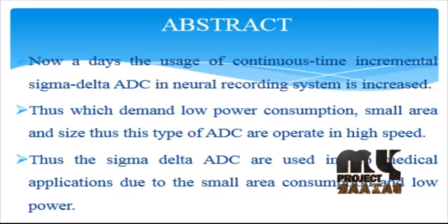This two-step architecture is also power efficient as the resolution requirement for the incremental sigma delta ADC in each step is significantly relaxed. To further enhance the power efficiency, a class AB output stage and a dynamic summing comparator are used to implement the sigma delta modulator. The prototype chip was designed for fabrication in a standard 0.18 micrometer CMOS process to validate the proposed